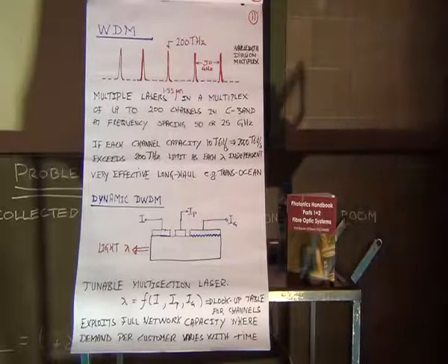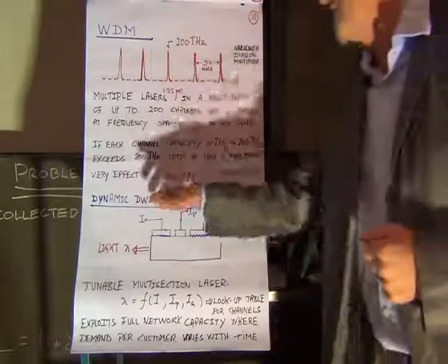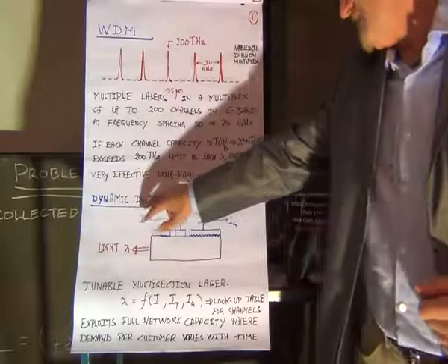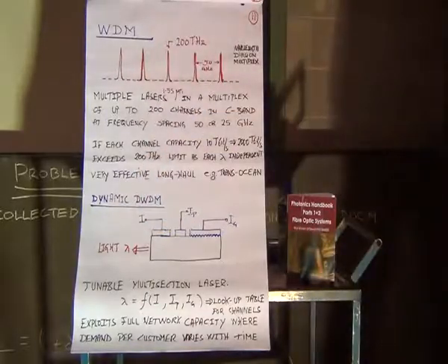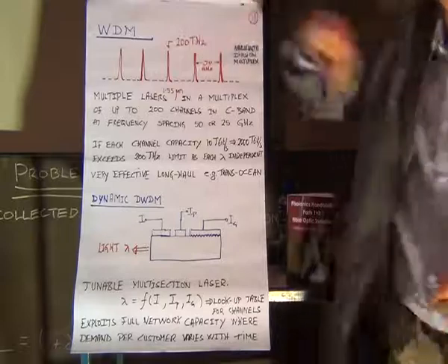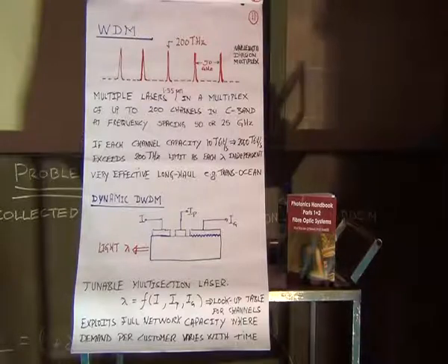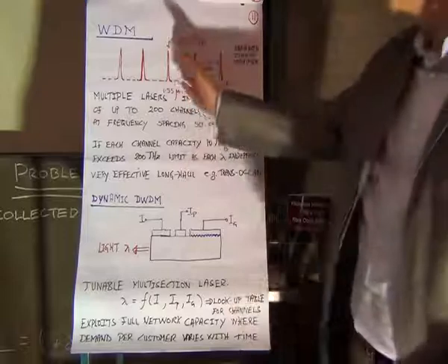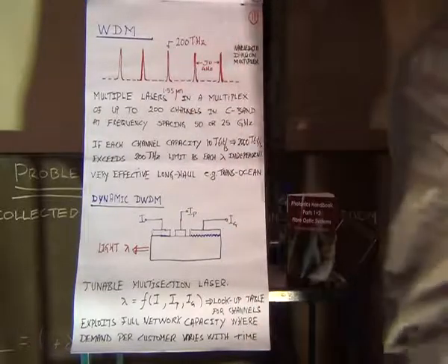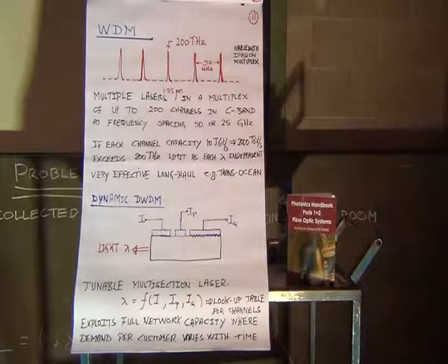Now that has the possibility for dynamic wavelength division multiplexing. And the D there stands for dense wavelength division multiplexing. You can actually bring this down even further to 25 gigahertz spacing. Okay, what could we do? We could say, look, it's past midnight. Everybody in Microsoft Dublin have gone home. However, there's a need for capacity in Hong Kong. So we could reassign their channel to a customer in Hong Kong for 8 hours or whatever, dynamically.